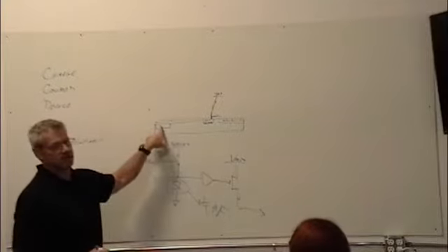Indium melts at like 90 C. So if you're out on a hot sunny day and your cooling's not on, they can actually melt. There's all sorts of things that can go wrong. But when you're talking infrared, you're talking cooled anyway, because you're trying to detect things that are hot. But again, it's expensive. You want some kind of resolution, it gets really expensive, really fast, because you've got to play these tricks.